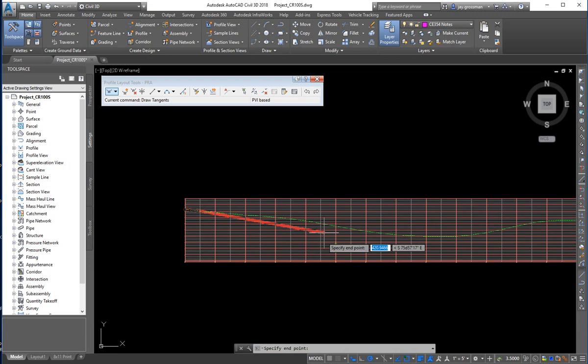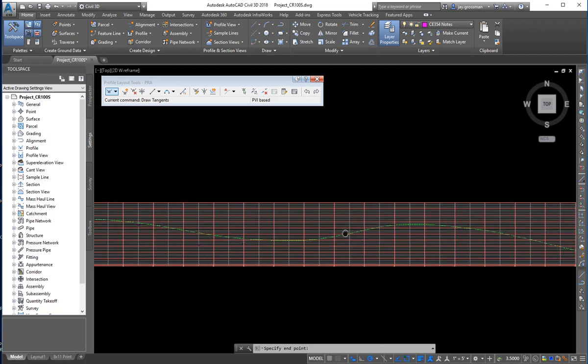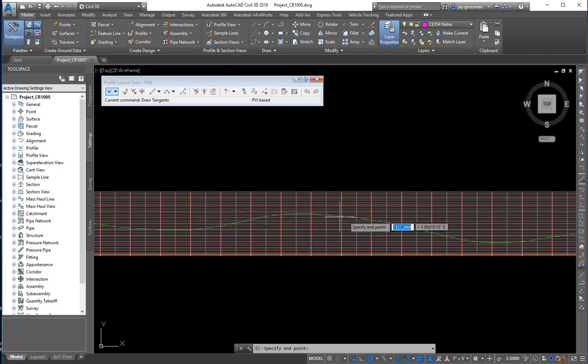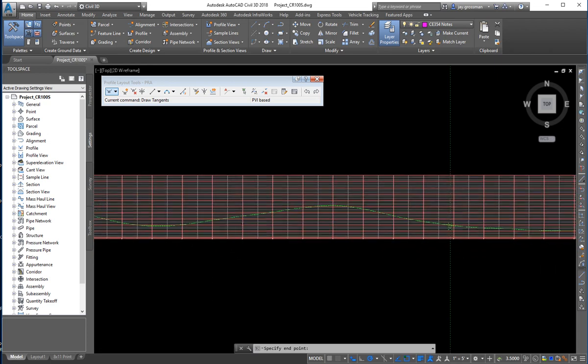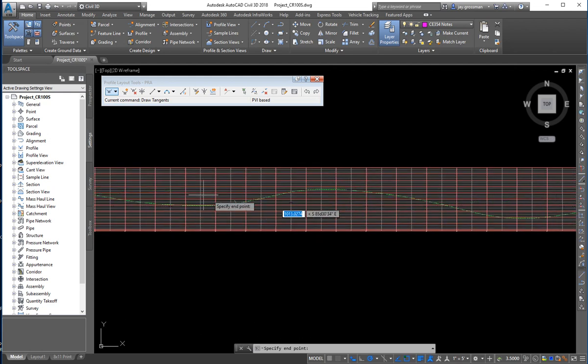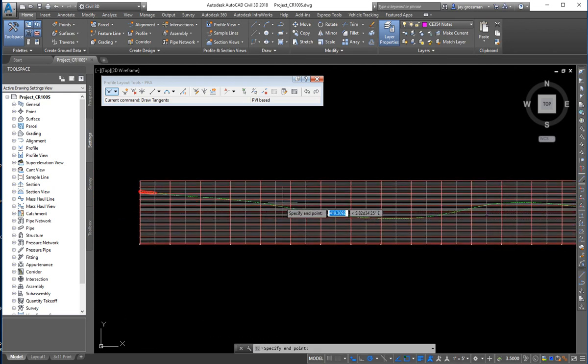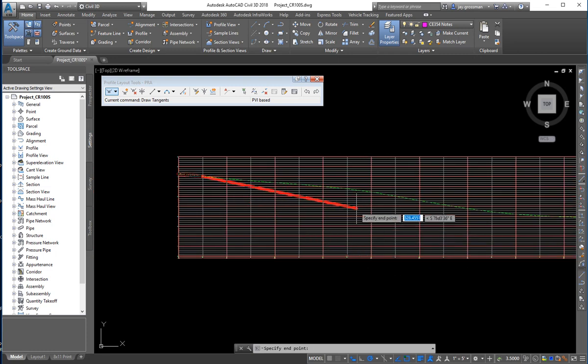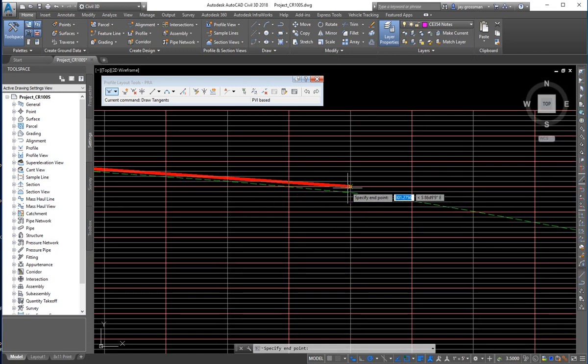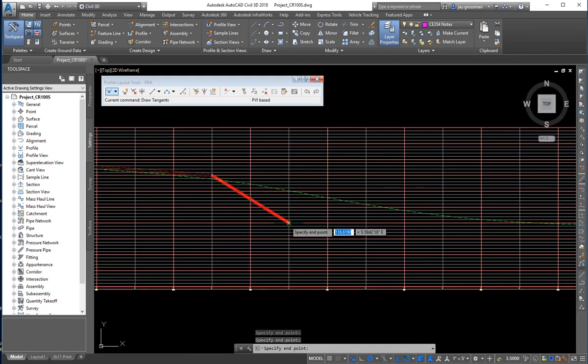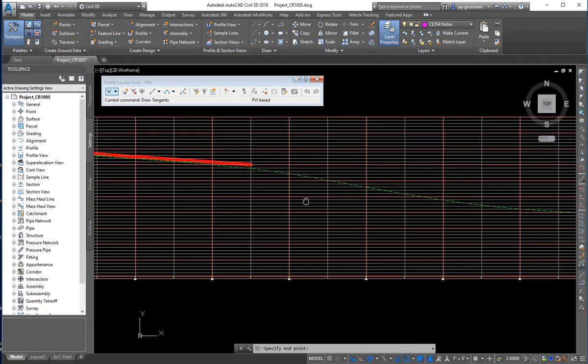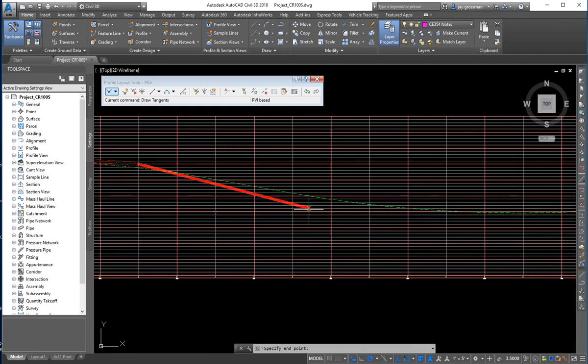So now we're going to zoom back out a little bit here. We've got a major hill here, so I'm thinking we're going to put one crest curve there and try to get one complete sag curve through, because we don't like to do multiple sags. And then another big crest, and then another big sag curve, another crest, and a little roller coaster out there. A lot of nice grade change. That's one of the reasons I like this project. So let's say our first one, we're going to have a PI somewhere in this neighborhood. I'm going to snap to the grid there, because that puts my PVI, point of vertical intersection, at exactly an even station, which isn't a bad idea, right?